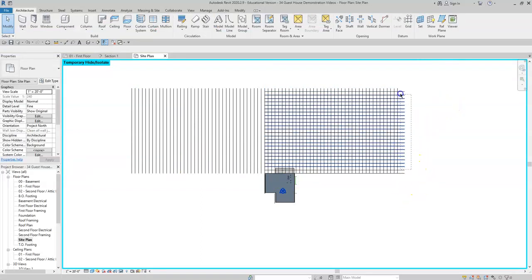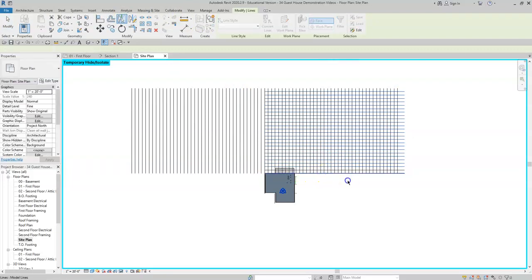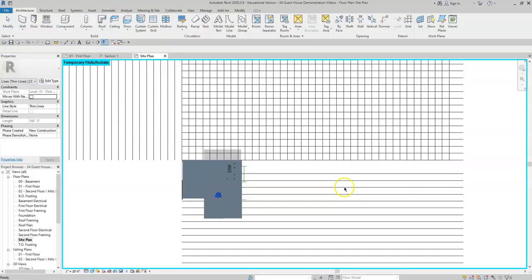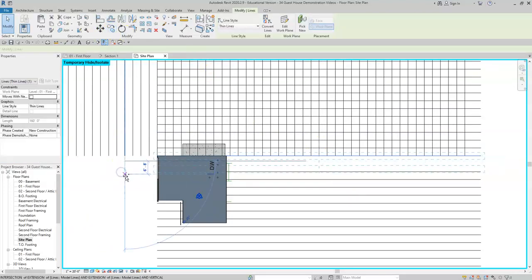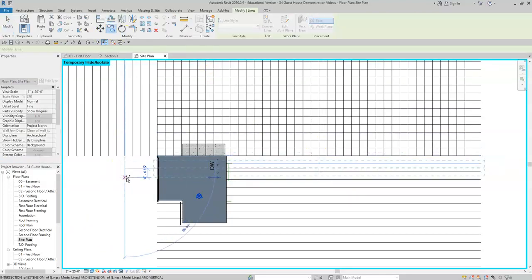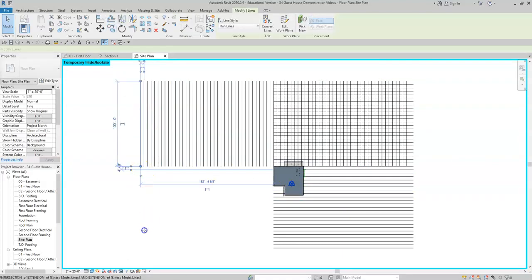I'm going to copy and I'm going to mirror. Okay. I missed one, but I know it's 4 feet, so I'll just copy it down. 4, enter. Okay. And now I'm going to use my extend command, and I'm going to make multiple lines extend